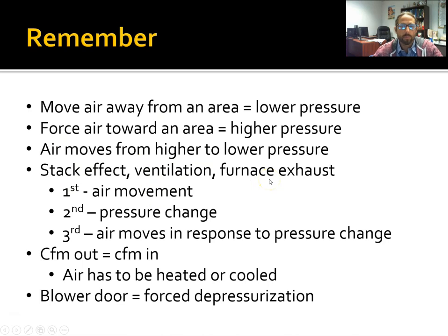So you move air away from the building, you're depressurizing the building, which forces the air to come in. Remember that for every cubic foot per minute out, the problem is that air has to be heated or cooled to make it comfortable, sometimes dehumidified, which we'll talk about later. And so there's an energy penalty for that. And then finally, we can use a blower door to force depressurization and actually do some analysis of a building.